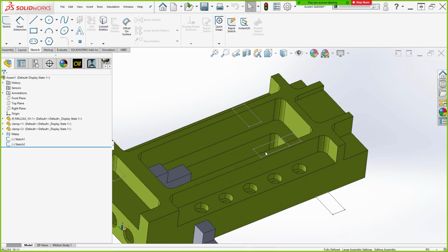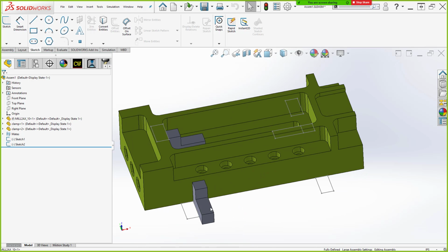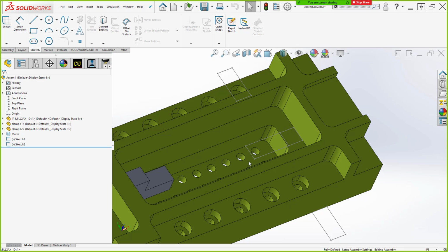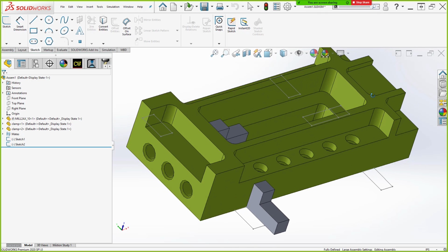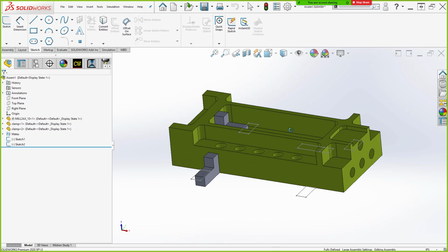It'll respect each height independently, and you can do a little bit more clever things there. So even if you don't have fixturing, which, once again, when I do my avoid areas, I'm still limited to just extruded shapes. I can't do any kind of curved shapes or anything like that. But if all you have is nice square clamps, then you don't even need fixturing, not even need assembly machining necessarily, and just use a combination of sketches.